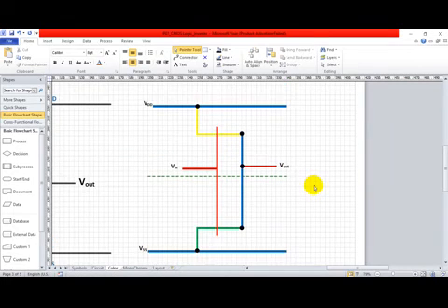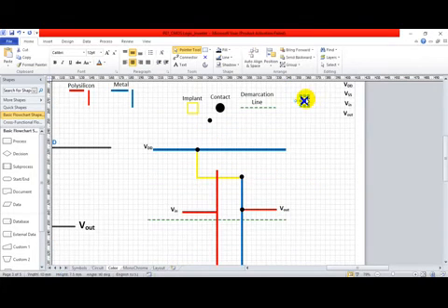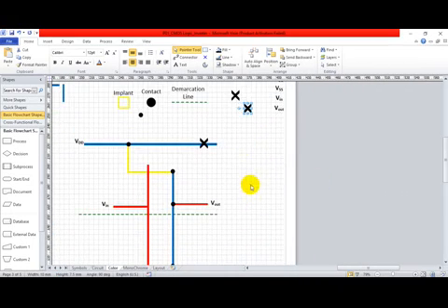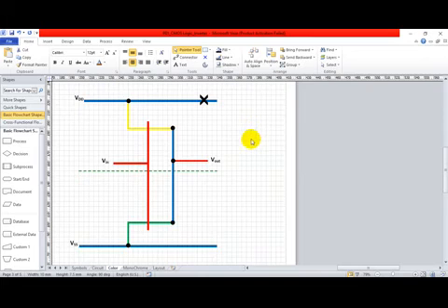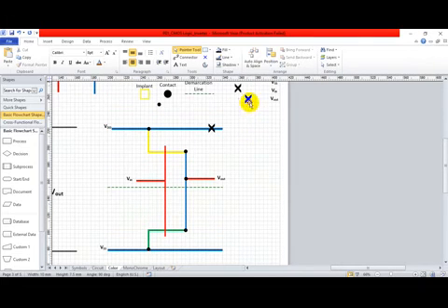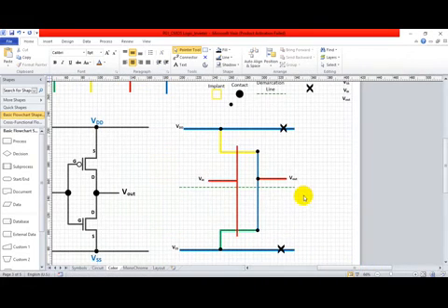That's it. You have to show the connections for substrate. So you can place a connection for substrate and a P mask. One on VSS, the other on VDD. So this is your stick diagram in the color coding form.